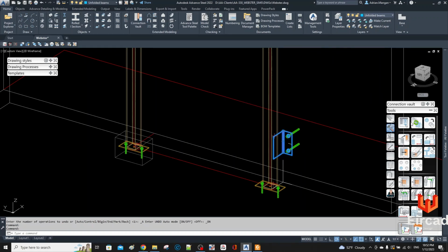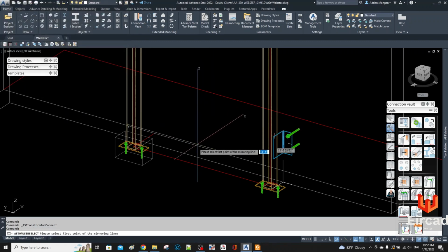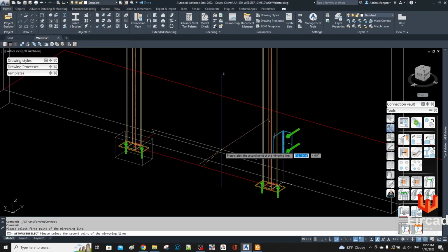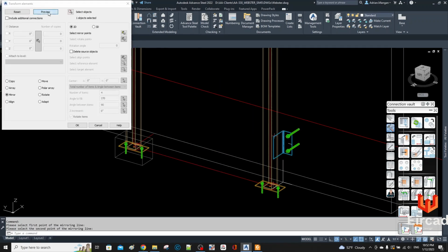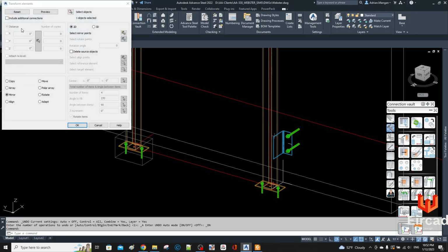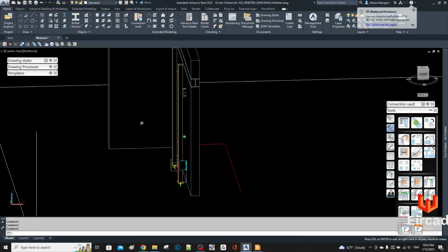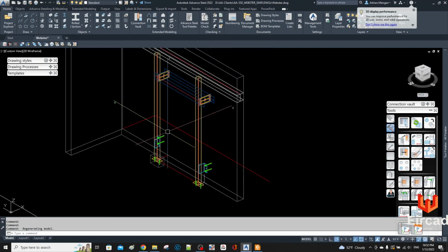Now if I select this, and I'm sure everyone knows this already, or most people do, and let's go to mirror, select mirror point, center this, preview, and that's what you get. You just get that clip. So let's modify that, select that, and okay. Alright, so that's good. I got those 2 clips in there.